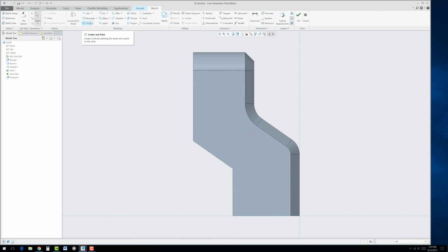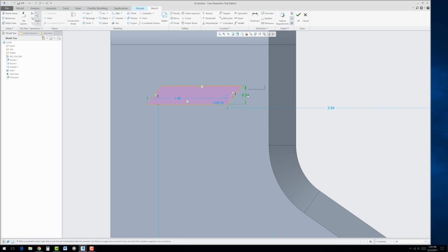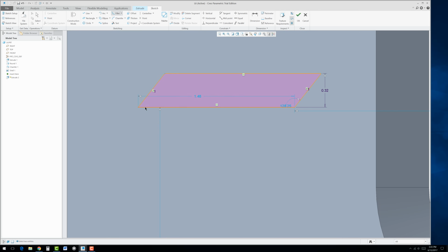And there's like a polygon of some sort, actually a parallelogram in here. So we'll go ahead and click and drop that right in there. Put the parallelogram in, and then set the dimensions according to the print. And then put the rounds in, and I would recommend putting those in here as sketch fillets, and just put some small ones in there. Again, follow the drawing,